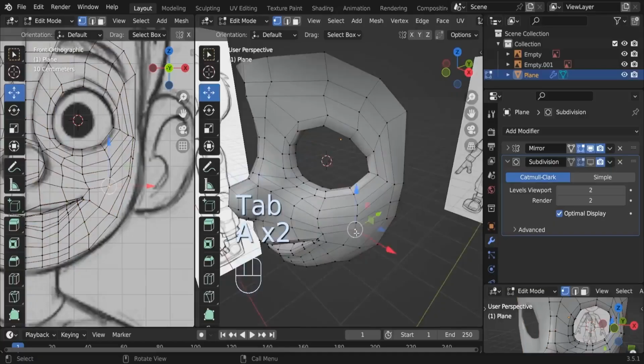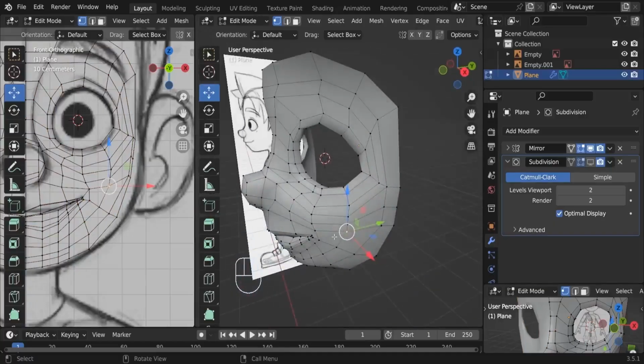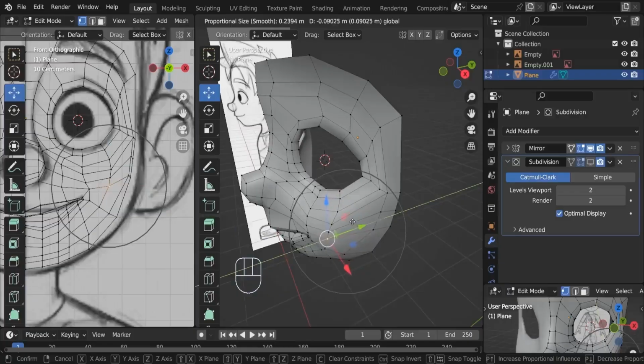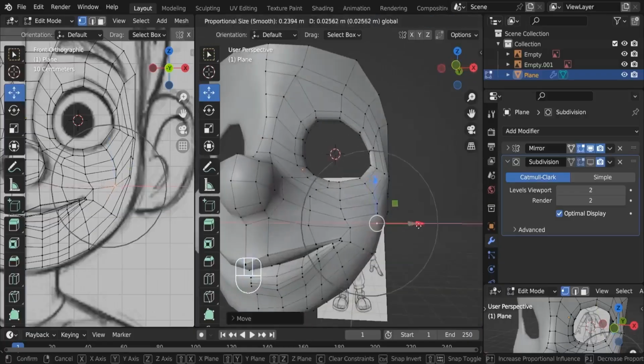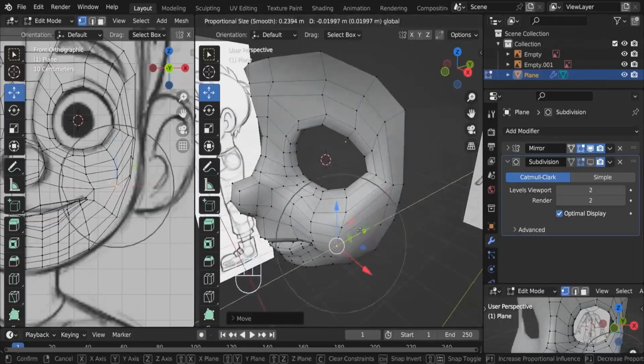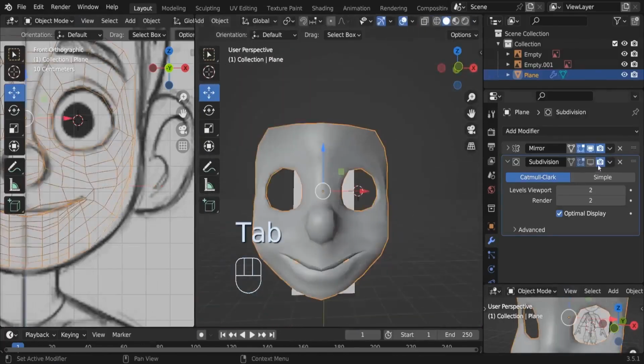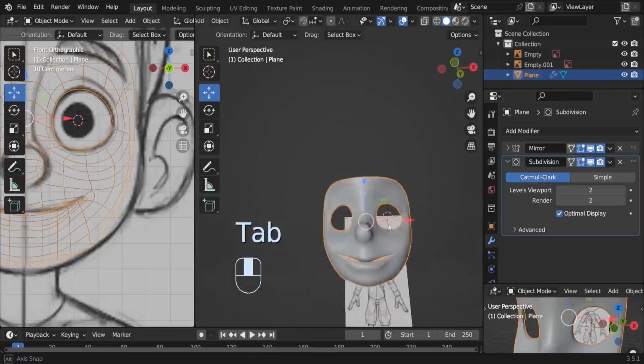I'd like to make it a little bit fluffy. So we can grab it from here. We can press O to activate this proportion editing. So this is the shortcut for activating it. And we can push this part a little bit outside. Also, we can take it to the right. Okay, so this way we're going to be having a cute character. All right, let me just activate the subdivision surface modifier and let's see.